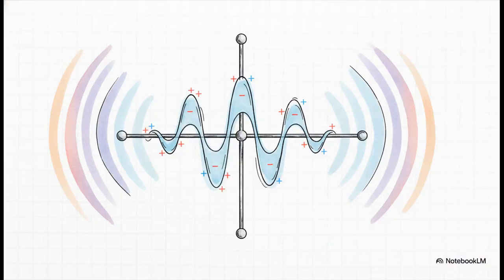So here's what's happening on the wire. You feed an alternating current into the antenna, and these electrical waves shoot out to the ends, bounce back, and then they crash into the new waves coming in. When you're at resonance, when that length is just right for the frequency, this crushing of waves creates this beautiful, stable, powerful pattern of energy. That's your standing wave, and that's the magic that launches RF energy out into space so effectively.